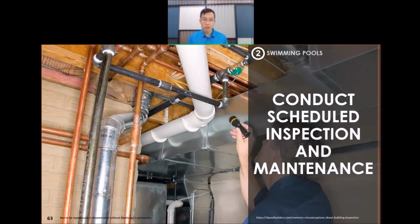I'm not just talking about the main structure. Sometimes you have sound systems that are locked down by stainless steel bolts or so on. Those areas could be hidden away, but they could have a catastrophic failure if they are failing. Okay, so do conduct a scheduled inspection for your building and all the accessories.